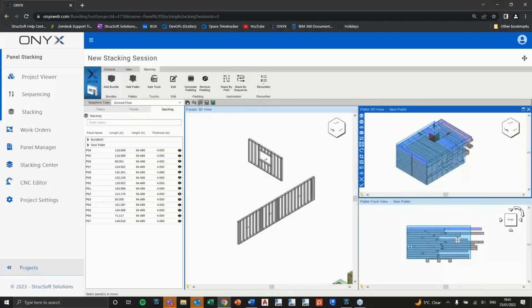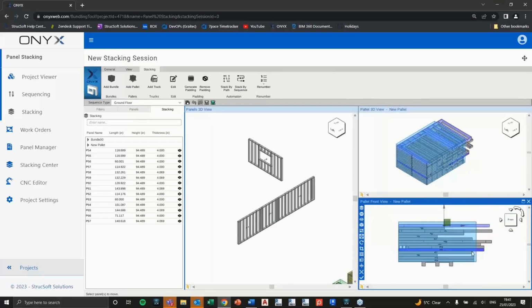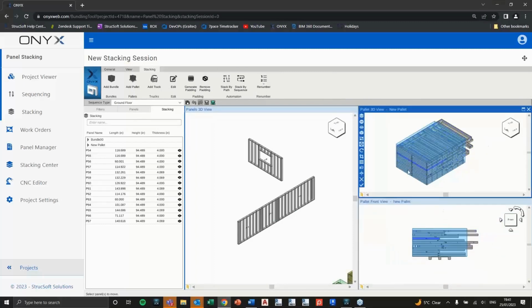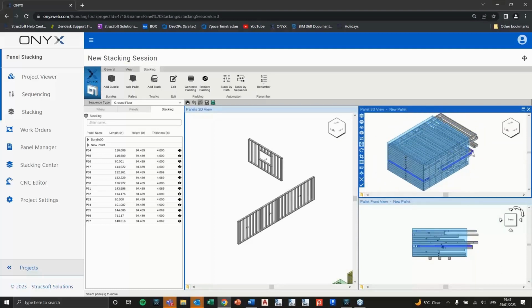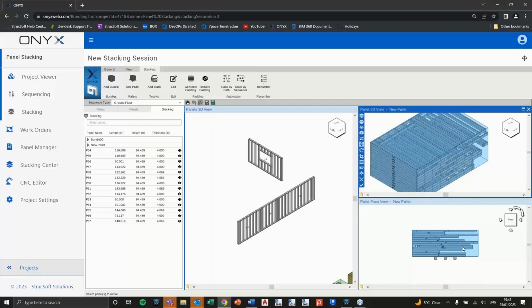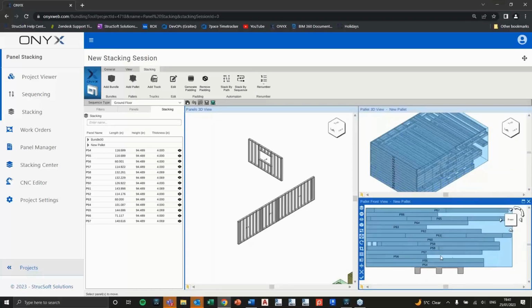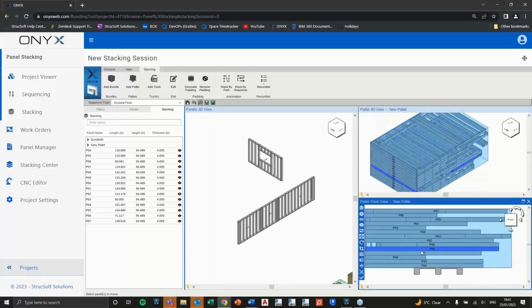We have all the panels that we selected in our container. And again, we need to clean it up a little bit. We need to extend it so it's actually enclosing those panels. So I can hit the shrink button. That will just resize around those elements. And if I wanted to add false panels, I can go ahead and do that. You can also group panels together as well.